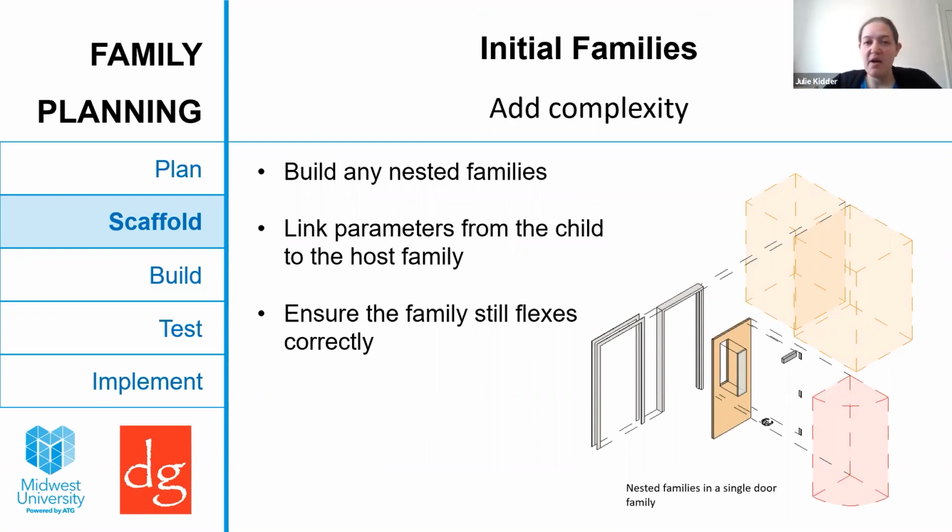And we are at the hour, but I'm happy to stay and continue answering a couple of questions I've got left. How did you handle curtain wall door panels versus the actual doors? The doors hosting in walls were built first. The curtain wall doors are true curtain wall doors, and they were built second.